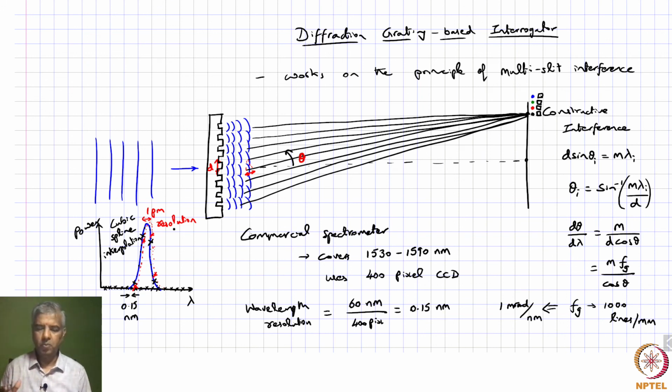However, before we move on, I should also mention that if you are looking at perturbations that are changing over a period of time, the other parameter that matters is how fast can you pick up the spectrum information. And that is limited by the fact that your CCD array, when it's reading all these values, is able to do so only in a sequential manner.